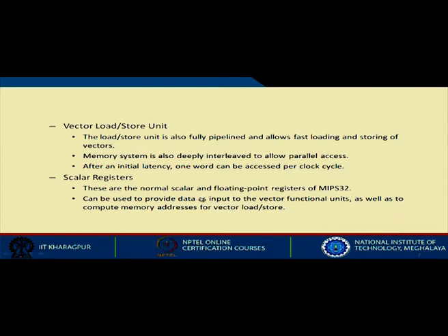There are some operations where you may want to add, say, a scalar number to all the elements of a vector, then the scalar number can come from one of the scalar registers. Okay. Moreover, you can also use the scalar registers to compute the memory address which will be used by the vector load store unit, from which memory address you want to load or store. Okay. So, scalar and vector registers can be used together.